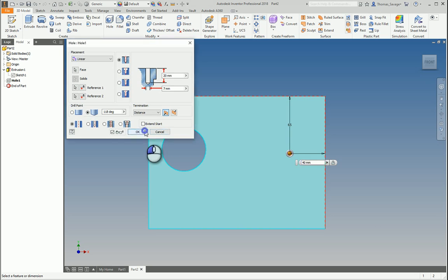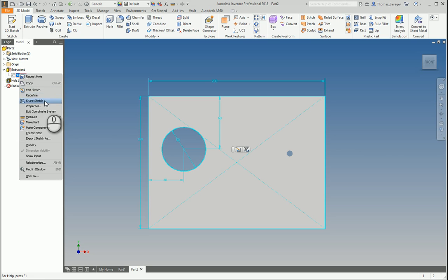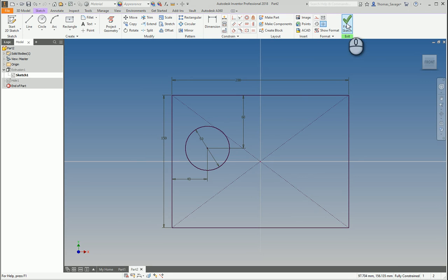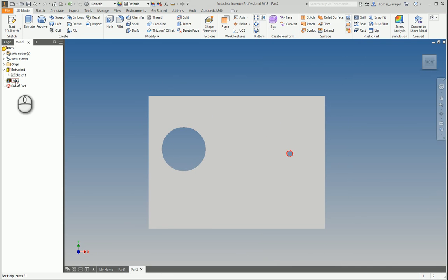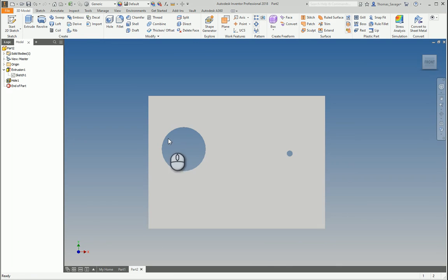Whereas if I want to edit the hole when I extrude, even though we haven't got much in the tree here, so it's a lot easier, but if I add 50 features, then I have to go back and find out which feature, then open it, and then edit through here. It just makes it messy, and it can just take a little bit longer. It's best to keep your sketches as simple as possible. You can also double click, they're there, change quickly. That's the best way to model.